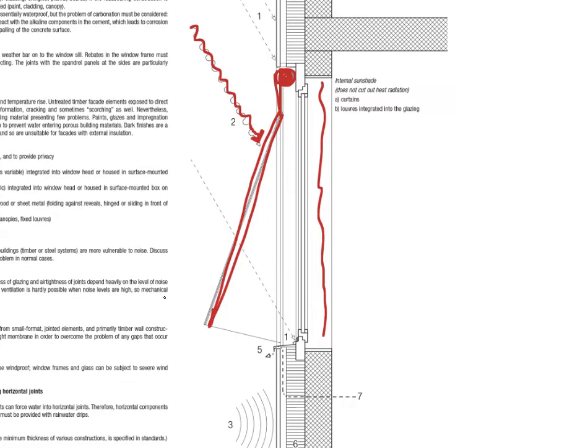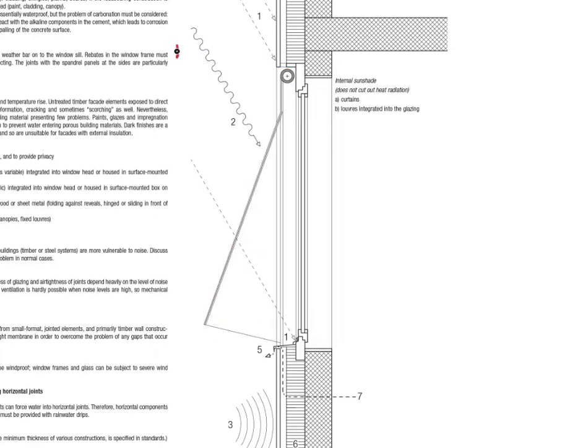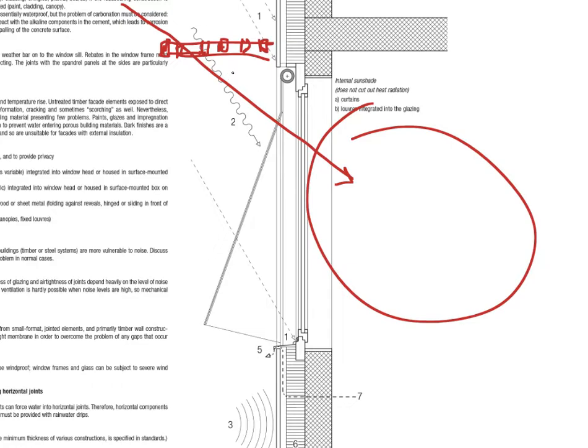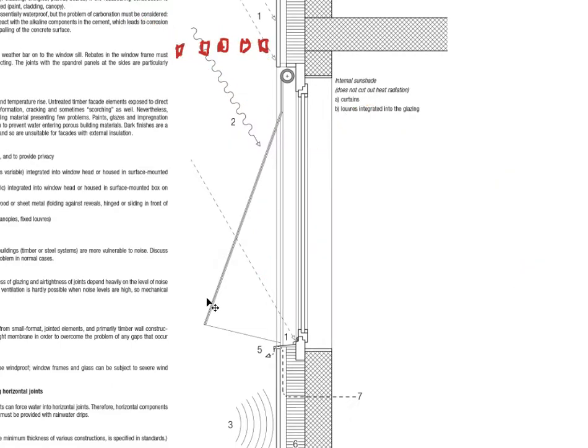Of course, there are also fixed external shading devices, such as sometimes we can see these brise-soleil, like little overhanging structures above a window, and they are usually designed in a certain way that they allow the winter sun, which is usually at the lower angle, to penetrate the window to actually have solar gains. And then when the summer sun, which has a higher angle, comes, they actually block that sun, making sure that it is efficient in both winter and summertime. So these are some basic different principles on how we can apply them.